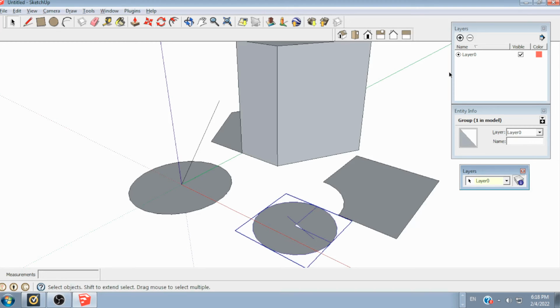So let me talk about layers a minute. Always, always, always draw things on layer 0. When I first started with this, people kept exhorting me to do the same thing, and I didn't understand it, but just take our word for it. You can stay in a lot less trouble if you draw everything on layer 0. Now, everything here is drawn on layer 0. It's the only layer defined.